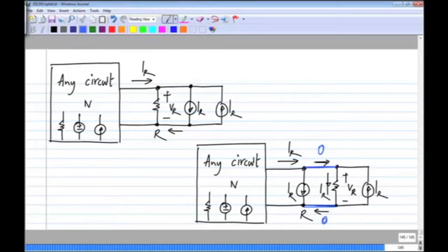So now if a wire is carrying 0 current, there is no point having that wire. I may as well cut it off. So this current will be 0. So I can cut this off and nothing will change in the circuit. Because whether I have an open circuit, that is a cut wire, or a wire with exactly 0 current, it is exactly the same thing. So it won't disturb the circuit. So I can cut off those things. So what is the bottom line here?